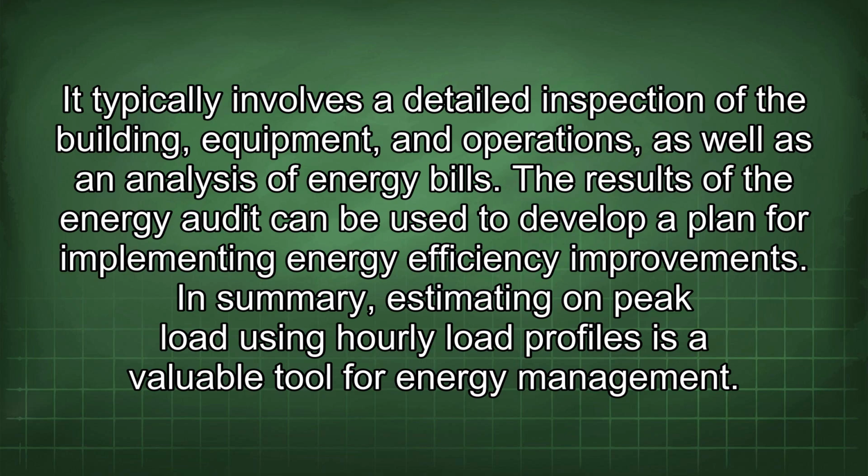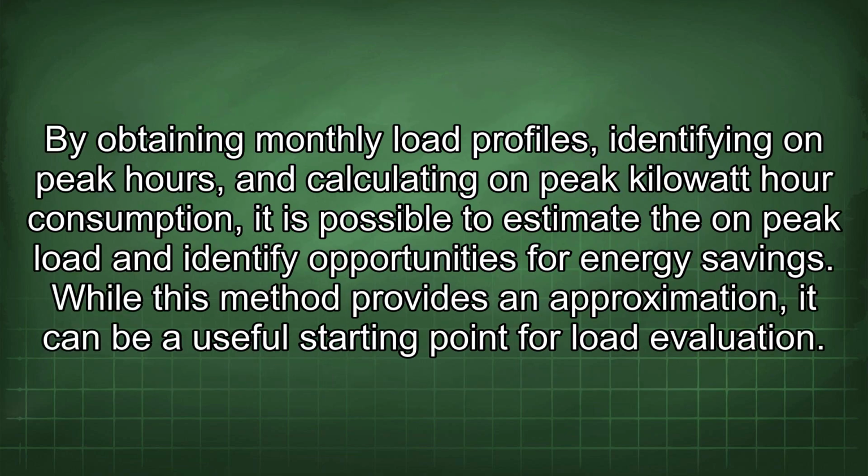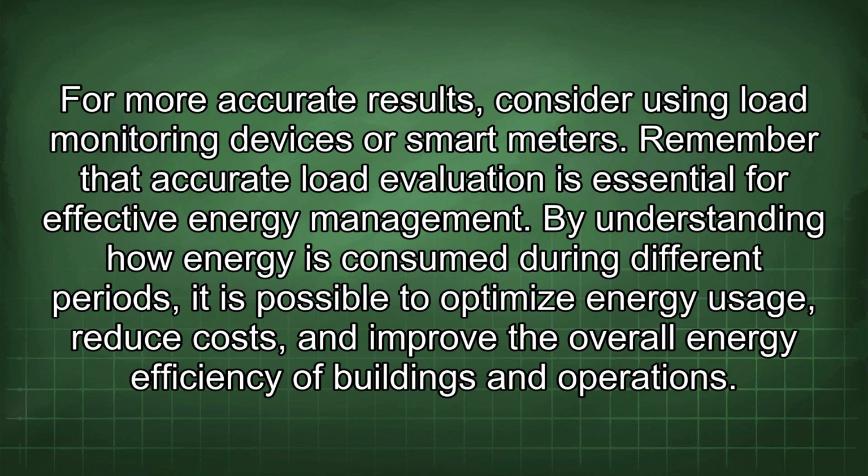In summary, estimating on-peak load using hourly load profiles is a valuable tool for energy management. By obtaining monthly load profiles, identifying on-peak hours, and calculating on-peak kilowatt-hour consumption, it is possible to estimate the on-peak load and identify opportunities for energy savings. While this method provides an approximation, it can be a useful starting point for load evaluation. For more accurate results, consider using load monitoring devices or smart meters.